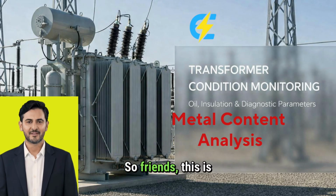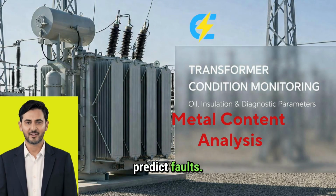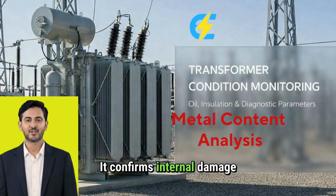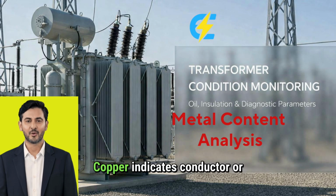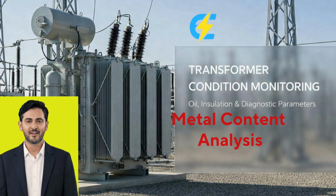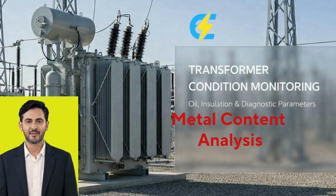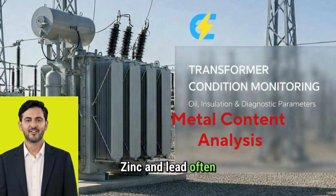So friends, this is the real meaning of metal content analysis. Metal analysis does not predict faults. It confirms internal damage mechanisms. Copper indicates conductor or winding issues. Iron indicates core, tank, or structural wear. Aluminum points to conductor or spacer degradation. Zinc and lead often come from coatings or solder.